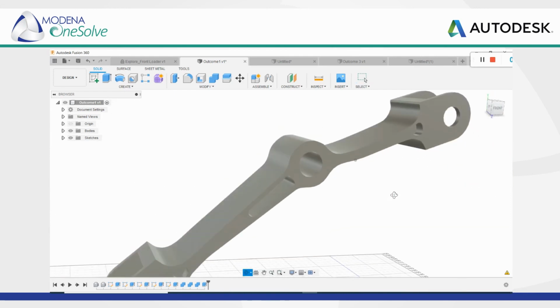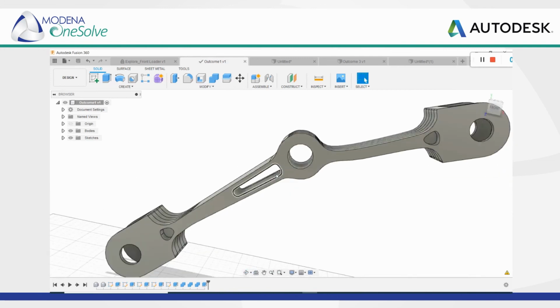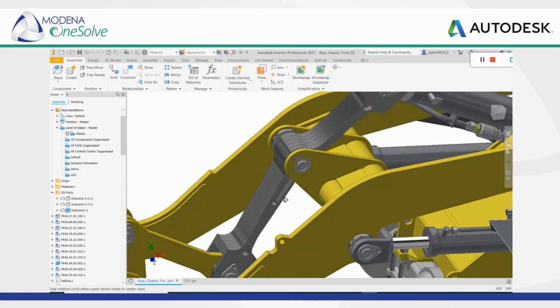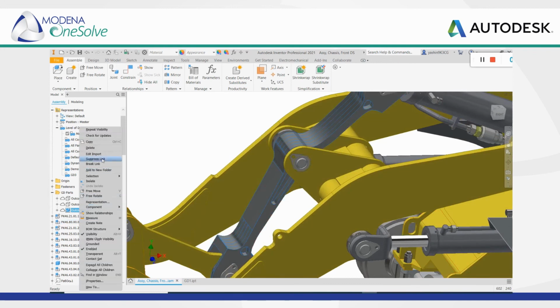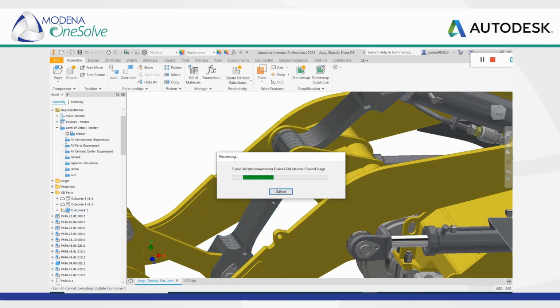So we have our cut that's been created inside of Fusion. I'm just going to quickly save this part to update any changes that have been made to it. So we've got that cut through the middle of the arm. Now, if I head back into Inventor, we should see that after we run an update, this part will also reflect that change. Check for updates. You can see changes have been made. There are updates available, as of course we've made a change inside of Fusion, and this will then reflect inside of Inventor. What it's going to do is process that information through the cloud.